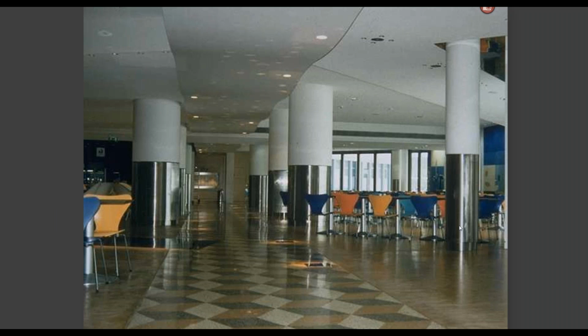In displacement, you'll notice that there are some chairs and tables that are placed very close to the displacement diffusers, but since this is kind of a cafeteria lunchroom type of space, we don't anticipate people sitting here for more than 2-3 hours at a time. So we're not concerned with the adjacent zones creating a problem. If somebody were sitting here for 8 hours at a time, that might be a problem, but this is somewhat of a transient space.